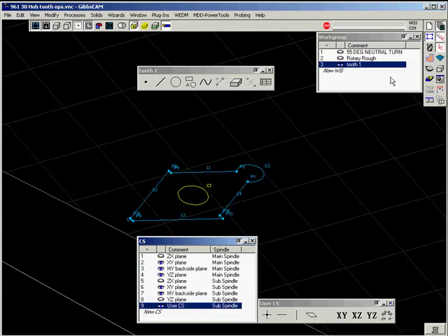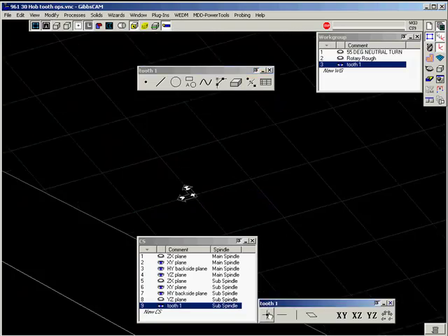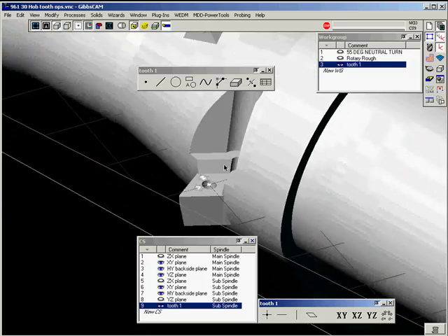I have geometry on the Tooth 1. I want to call this Tooth 1 coordinate system so that I can remember which one's which. I'll use the center point of this circle, and we'll extract that like we normally would, to be my origin of this coordinate system. So by just pre-selecting and clicking on it, now you'll see that my origin of the coordinate system is there. If I turn my solid back on, there we are.